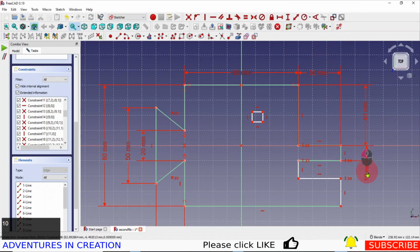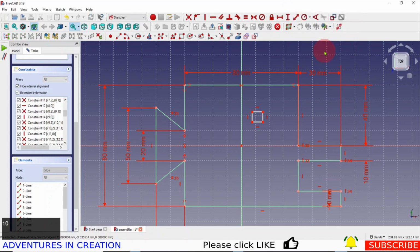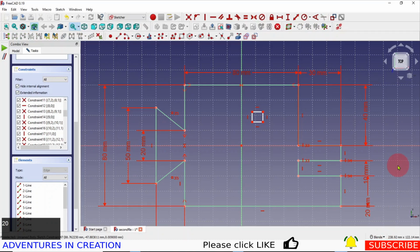Let's bring that one out here. And I know from my sketch again that this guy here is also 10. Oh, that's not true. It is actually 20. So I'll show you how you edit a dimension. You highlight it till it's yellow, double click it, and then I can change it to what I need it to be. So it is 20.